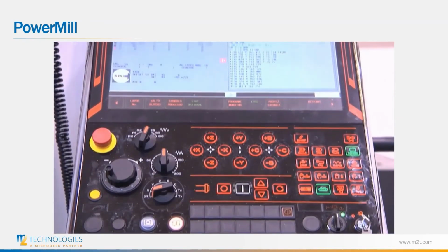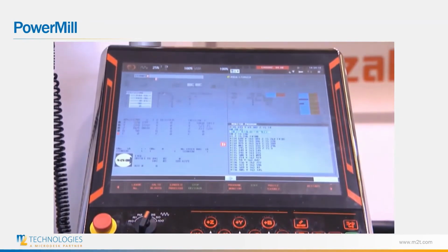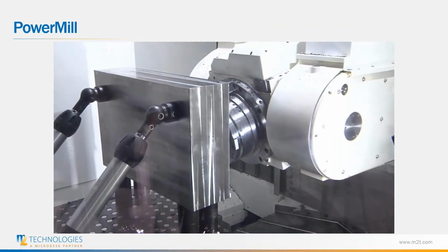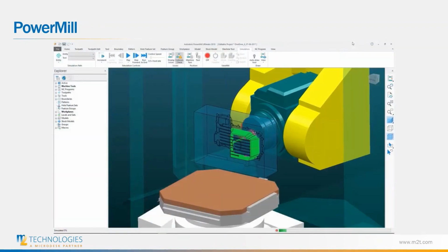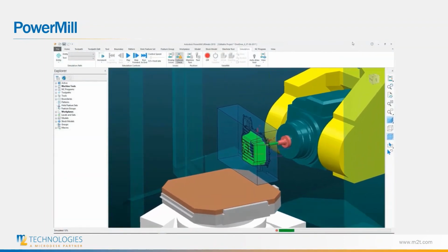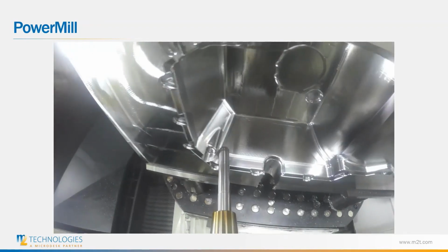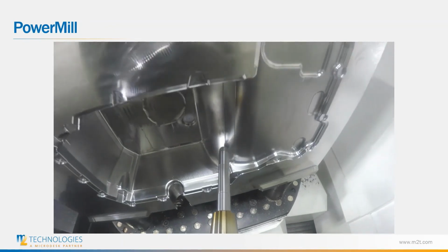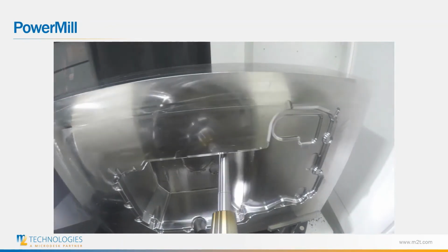Finally, all PowerMill 5-axis toolpaths benefit from intelligent tool axis smoothing, avoiding sudden and erratic machine motion that could result in dwell marks appearing on your milled part. Smoothing will also allow your 5-axis CNC machine to complete the milling cycle faster, saving yet more time.